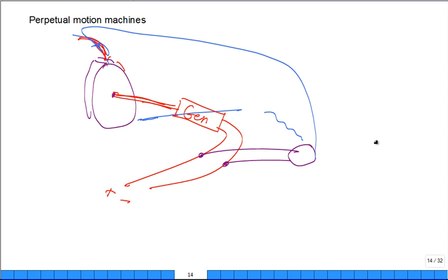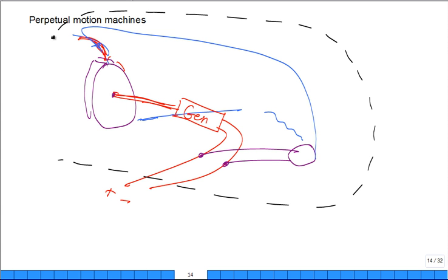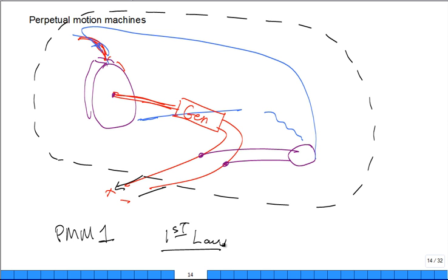That's a perpetual motion machine. Because if you draw a control volume that goes like this, the pump, the generator, the water wheel, the lake, and so on, is all within it. What do you have? You just have free-flowing energy coming out of a box perpetually. And so what does that violate? It's a perpetual motion machine of the first kind because it violates the first law, meaning that energy is being produced in this design. I just threw that one together very quickly, but that's an idea of the perpetual motion machine of the first kind.